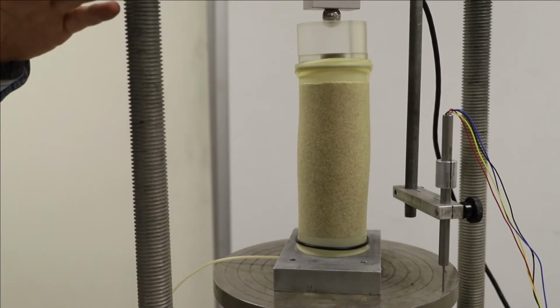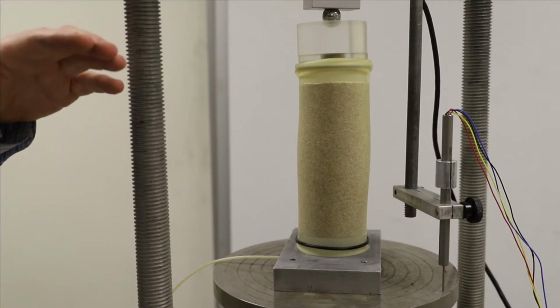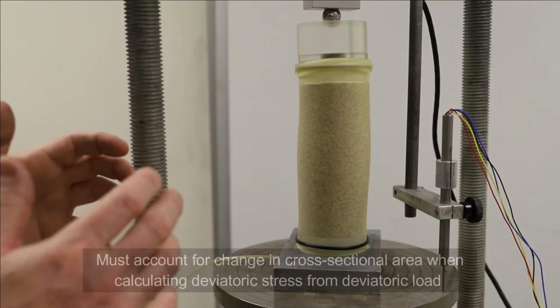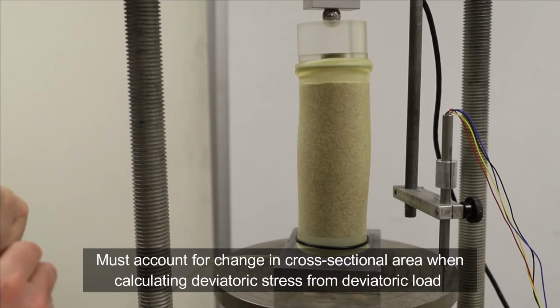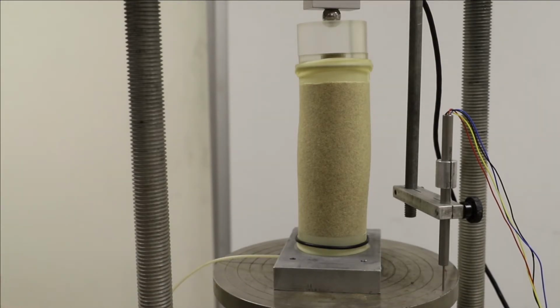And that makes sense. As we squeeze something vertically, there might be some volume change, but even if there is, there's going to be a tendency for the sample to get wider. And we're going to actually need to account for that when we calculate what the deviatoric stresses are, because those stresses are based on the vertical load and of course what the cross-sectional area is. And so that's changing as the test goes on, so we'll need to account for that. We'll take it further to failure.